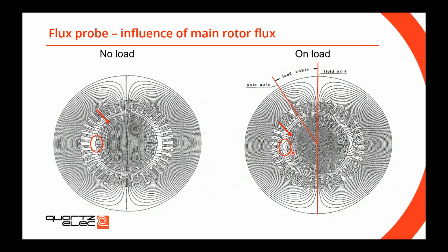Then if you change the load angle, which means you change the power output of your machine, that clear spot moves to coils 3 and 4. You continue doing that from power output 0 to your rated power by changing the load angle, so you can have a clear spot and highest sensitivity on each and every coil. I hope it makes sense. It's not easy to understand, but I hope it makes sense now, at least a bit more.